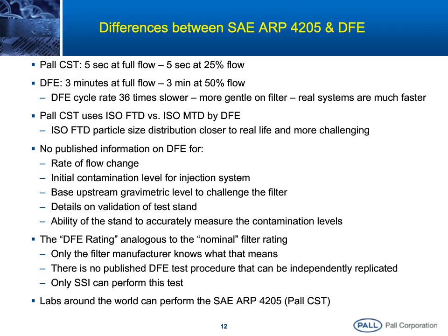The next major difference is the test dust. Isofine test dust used by the SAE test is more challenging for fine filters as it has more finer particles, and unlike the isomedium test dust used by the DFE method, it does not tend to form cake on the filter, which can lead to higher removal efficiency by virtue of the cake and not the filter media itself.